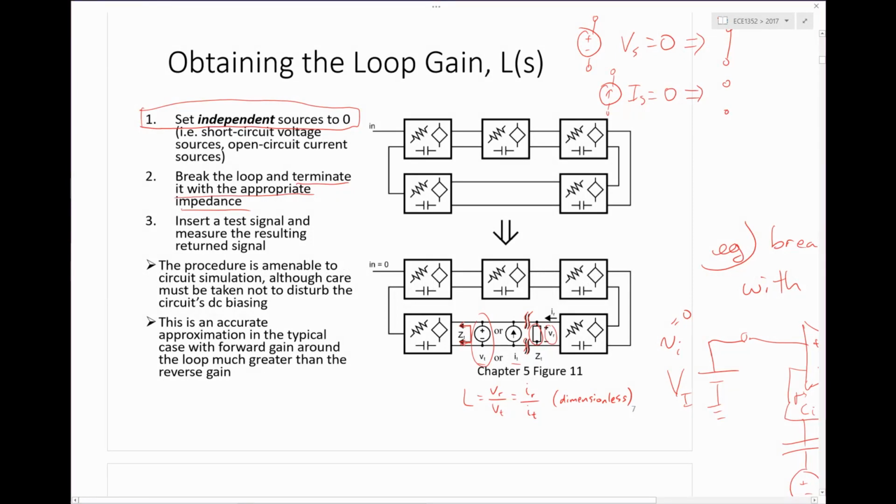That's true. Usually we assume, anyway, in this course we'll assume that beta is just a constant made up typically out of passive components, right? So either only resistors or only capacitors that form a kind of divider, current divider or voltage divider or something. So we assume that beta is less than or equal to 1 because it's just passive, and that it's just ratios of component values, so it's not frequency dependent.